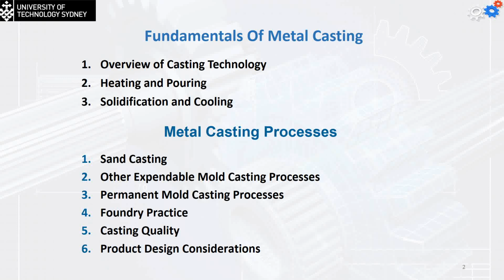Now that's different. You saw in the video, we talked about a temperature slightly higher than the melting temperature of the metal. Because if I just get to melt the metal, it's not going to be viscous enough to be poured, and it's going to solidify before it fills the cavities. So we have to talk about something called the pouring temperature. And then we're going to discuss the solidification and the cooling process after we fill the cavity.